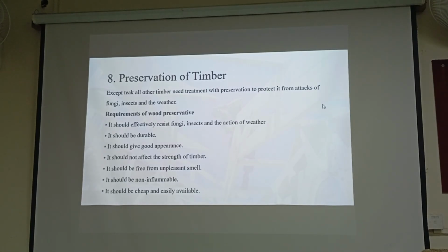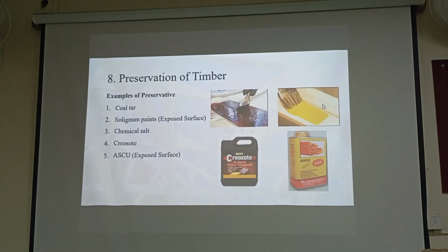Preservation of the timbers can be done through different methods, and basically preservation is done to make the wood effectively resist fungi, insects, and other action of the weather. It makes it durable, improves its appearance, increases the strength of the wood, and also removes unpleasant smell. The preservative should be non-inflammable so that it cannot catch fire, and it should be cheap or easily available so that timbers can be preserved easily anywhere. So these are the preservatives which are commonly used in India.